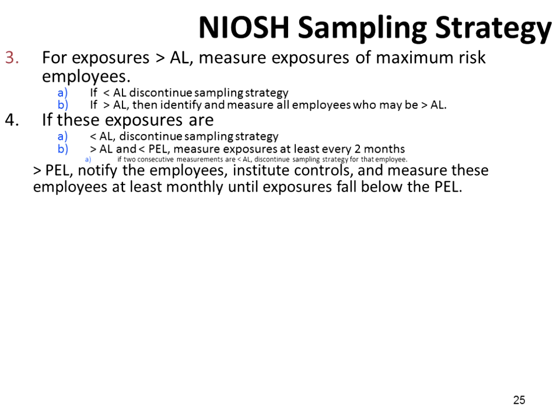If workers exceeded the action limit, then we need to identify which measures need to be put into place to bring people below the action limit and start to implement a more repetitive sampling program, where we will continue to sample every 2 months until workers have been brought down below the action limit.